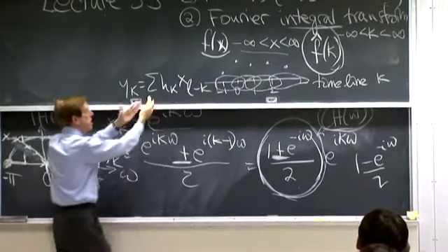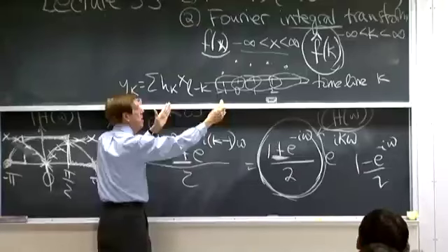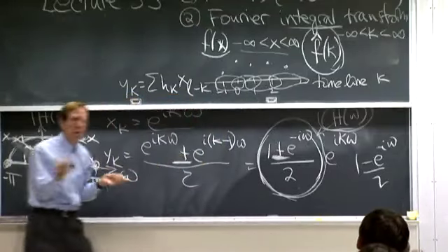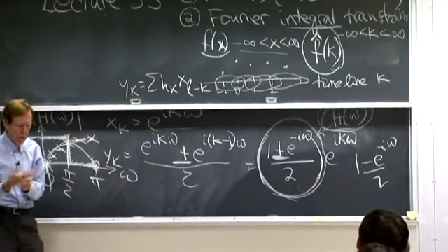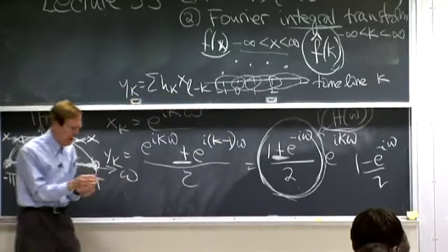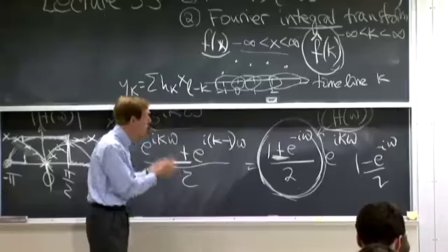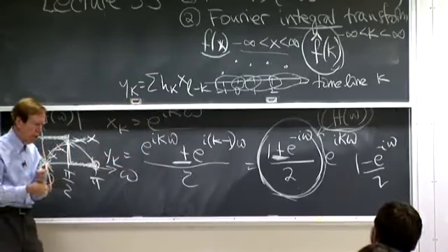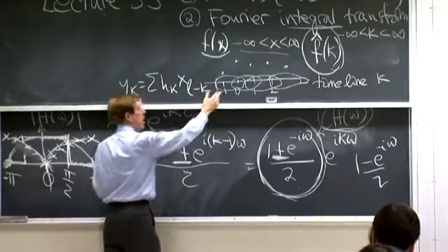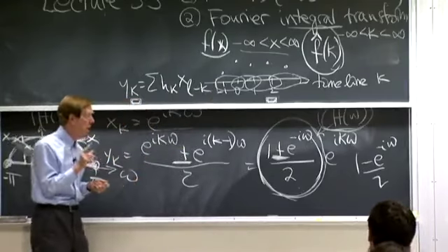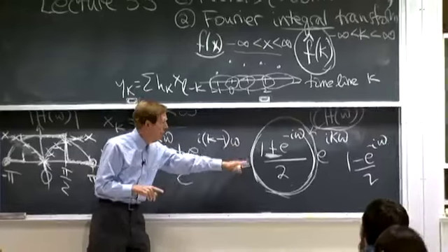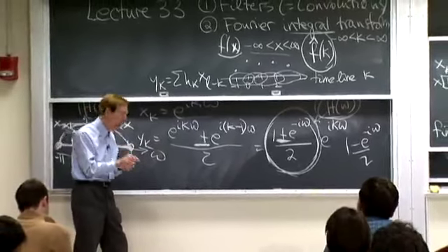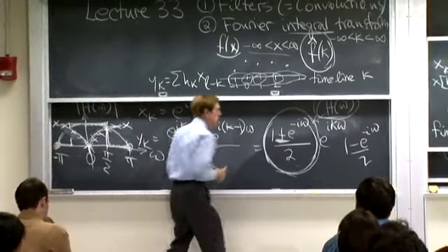So the window is the width of the h's, and as that window moves along, you could design a little circuit that would do exactly this, that would do the convolution. You just have to put together some multipliers, because you have these h's, these like halves, and you have to put in an adder that'll add the pieces.